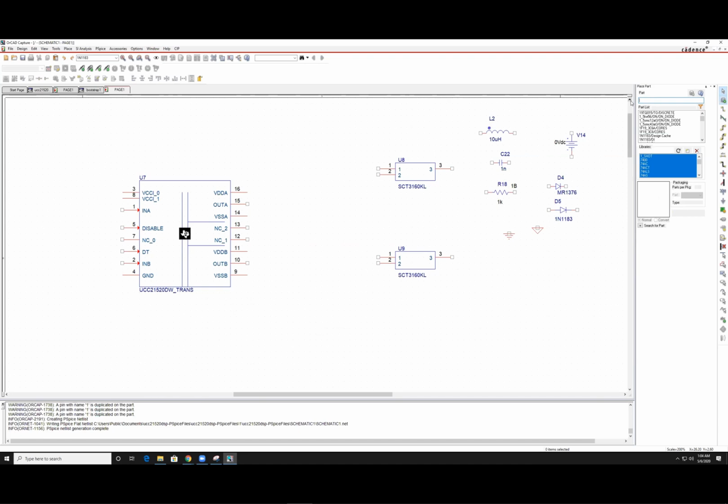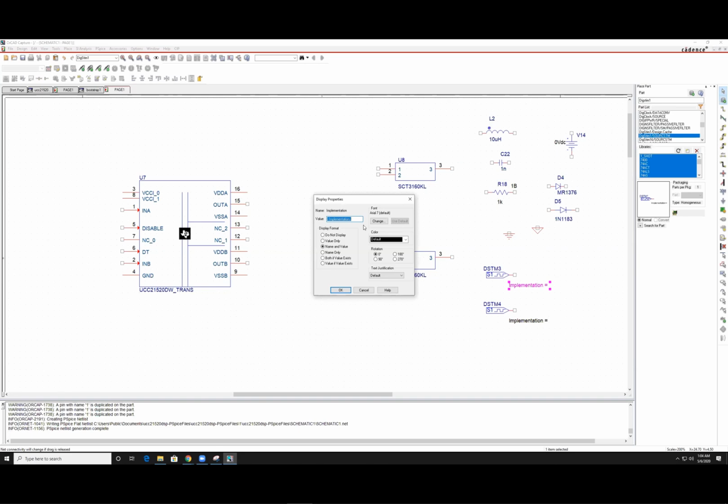Lastly, we'll need a digital signal that will provide the PWM signal. So go ahead and just type DIGSTIM1. We'll need 2 of these, one for the high drive and one for the low drive. To change the value of this, we actually just need to double click and set the name for it, INA. We'll go back to this later when we set up the simulation. INB. To change the values of these, just double click and set your desired value.